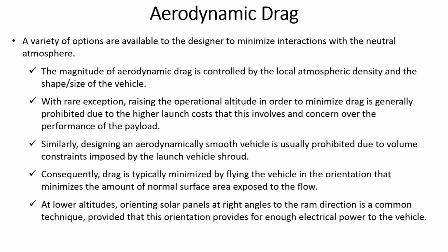At lower altitudes, orienting the solar panels at right angles to the RAM direction is a common technique. Of course, one thing has to be kept in mind, that is electric power, which should be the optimum electric power of the vehicle. So, these are all the methods and techniques related to the neutral space environment that I discussed, especially atomic oxygen attack, then aerodynamic drag, then hypervelocity impact, then debris.